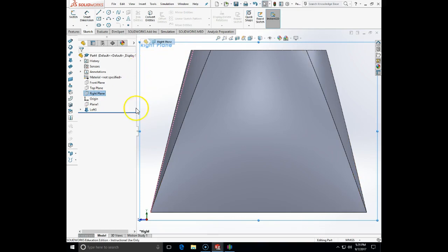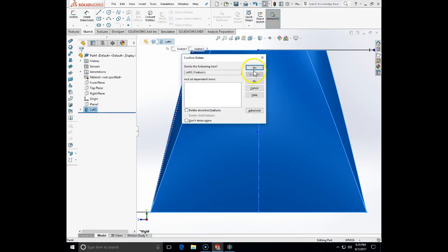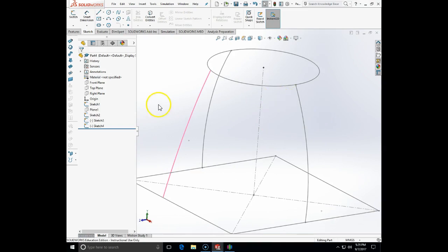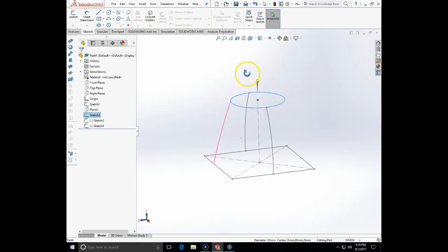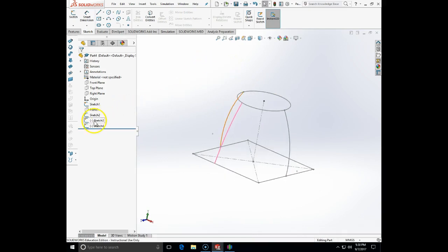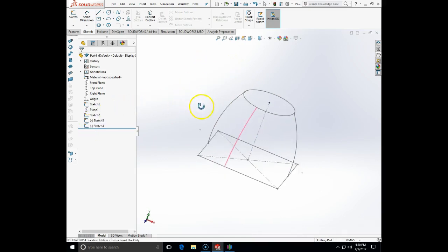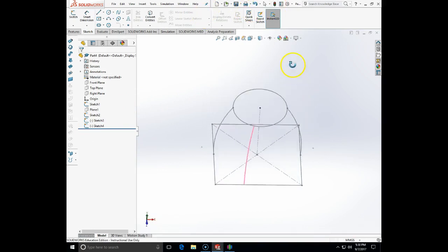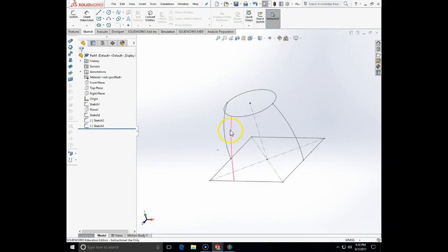And before I actually edit that sketch, I'm going to delete my loft or roll it back, because I will need my other guide curve too. Yeah, this guide curve is an artifact.